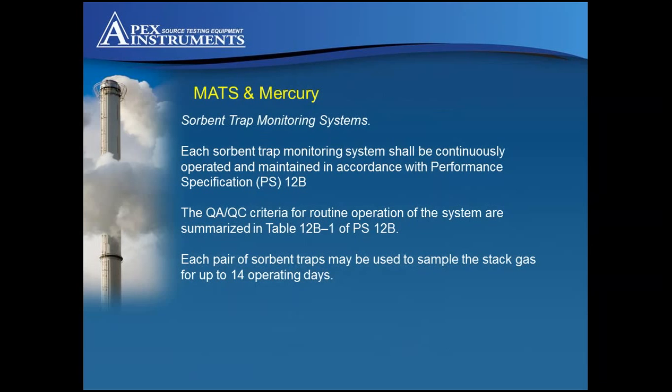Each sorbent trap monitoring system shall be continuously operated and maintained in accordance with Performance Spec 12B. The QA/QC criteria for routine operation of the system are summarized in Table 12B-1 within the Performance Spec. Each pair of sorbent traps may be used to sample the stack gas for up to 14 days. However, in our experience, 7 days is more of a normal operation.